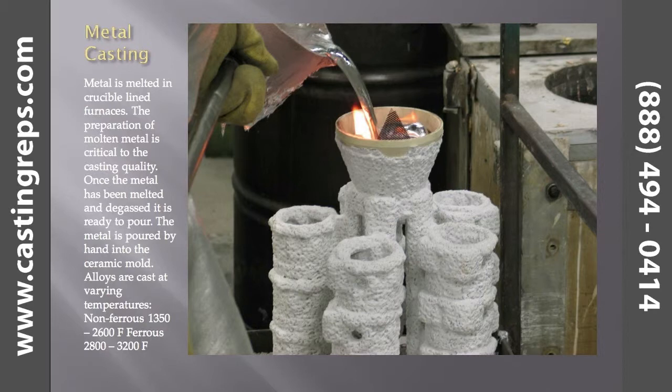The metal is poured by hand into the ceramic mold. Alloys are cast at varying temperatures. Non-ferrous, 1350 to 2600 degrees Fahrenheit. Ferrous, 2800 to 3200 degrees Fahrenheit.